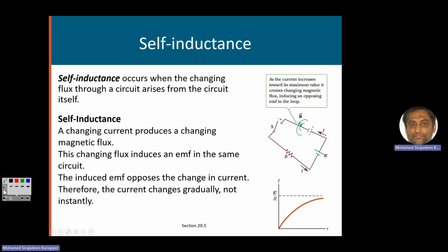Okay, so we discussed the motor again, which is the effect of the back EMF. Now we come to a new section, self-inductance. What we mean by self-inductance: imagine you have a simple circuit, a battery connected to a resistance, with a switch. When you close the switch, let's say this is 10 volts, and let's say this is 2 ohms.